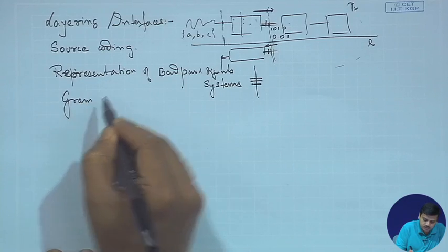And then once we have the binary sequence, we need to now send this binary sequence across through the channel to the receiver. And before we do that, we must use some notations which we have described and certain relationships. And now is the time that we look into the details of this particular system, so that we can use whatever we have developed before in subsequent establishment of the communication systems, as well as analyze the performance in later courses. So, the next important thing, of course, what we did at some point was the Gram-Schmidt procedure.